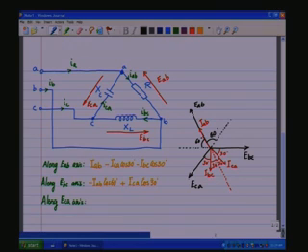Now, ICA is exactly 90 degrees from the ECA axis, and therefore there is no projection of ICA on the ECA axis. IBC has a projection on the ECA axis, which is IBC cos 30.